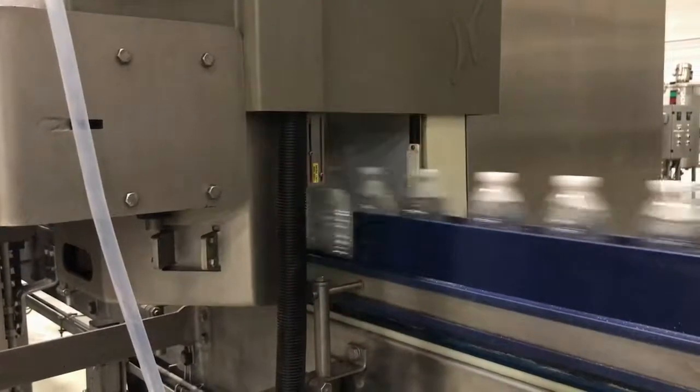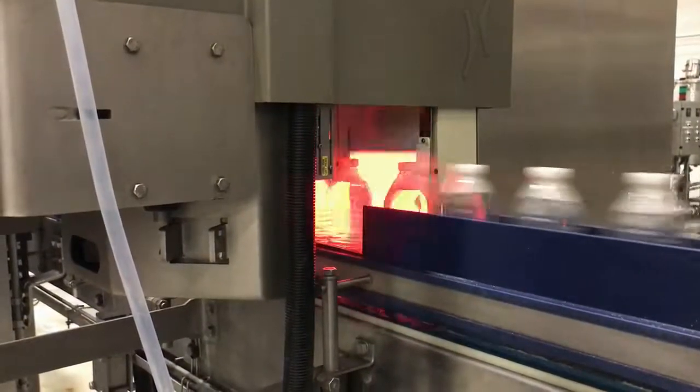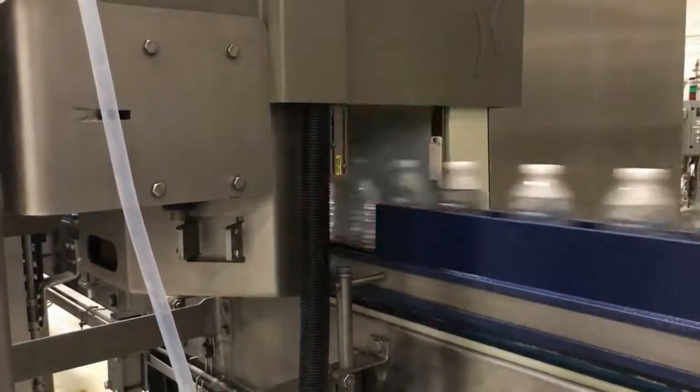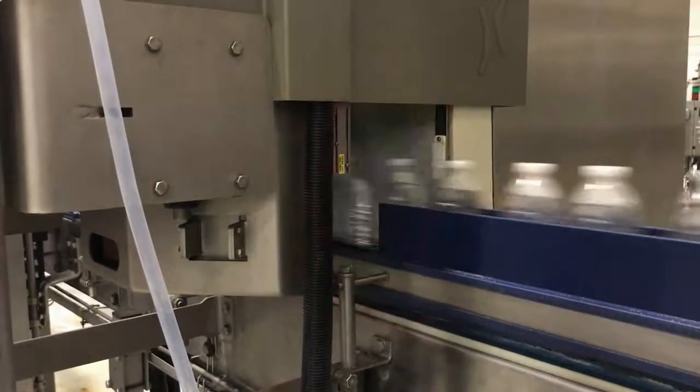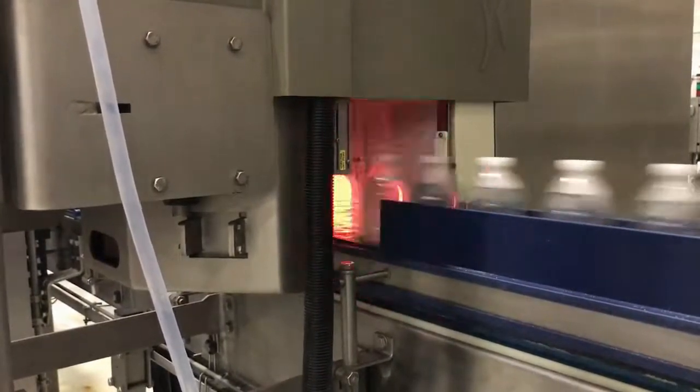The next CQP is the bottle date code application. This prints information about when the water expires, what time of day the water was bottled, and on what production line. This is a CQP because if the customer cannot read or identify this information and there is an issue with the product, it will be hard to track down the cause of the problem.